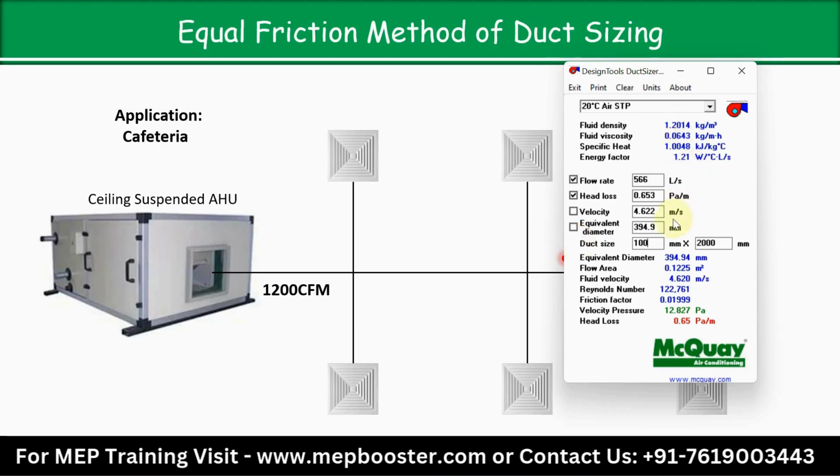Okay, so when I select the height 100, we get the width 2000. Now when you calculate the aspect ratio, width divided by height, 2000 divided by 100, you will get 20. So the condition is not satisfied, because the aspect ratio should be between 1 and 4. It should always be greater than or equal to 1 and less than or equal to 4.